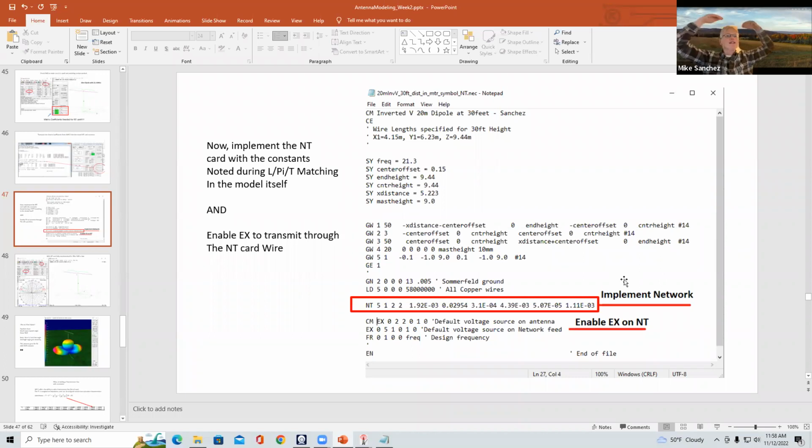And then here is a really interesting question. For the flat top, explore how the SWR looks as a function of height. It'll take 5 minutes in the symbolic format to answer the question. If I put my dipole at 5 feet, 10 feet, 20 feet, 40 feet, 60 feet, 200 feet, how does it change? It's just those kinds of things which are so fascinating to learn. And where is the best gain? Does the gain get better as it goes lower or higher? You guys already know the answer, but show it in the simulation.